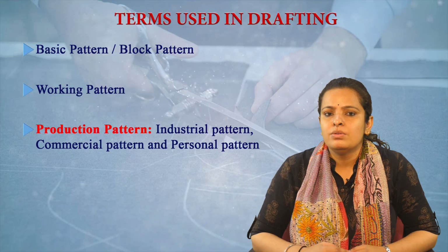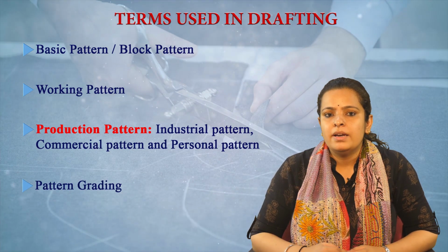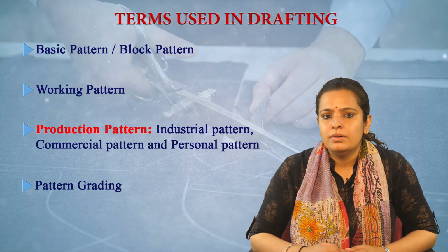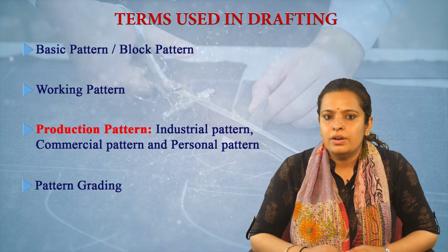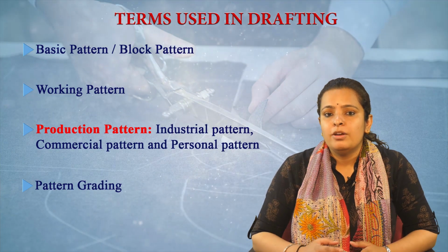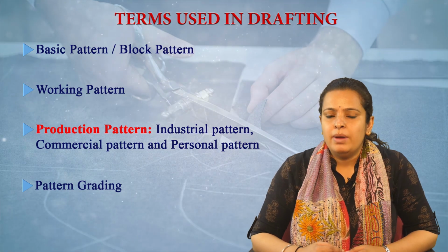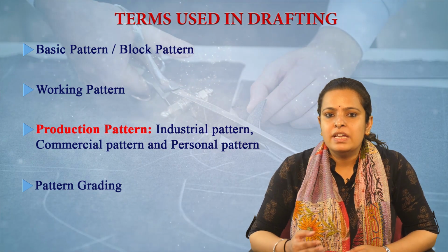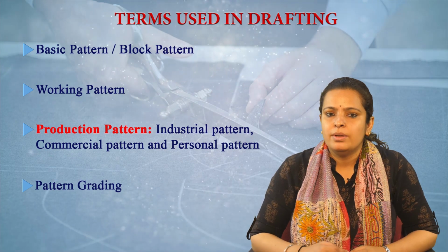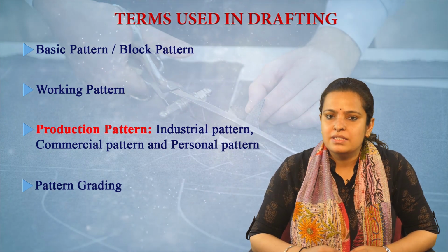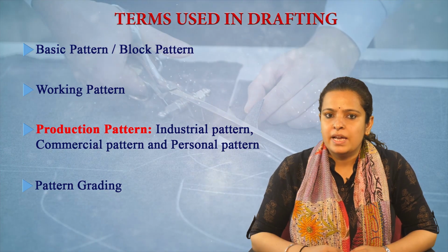Then we use a term called pattern grading. In pattern grading, we create a size range of a particular pattern by manipulating the size of the pattern, in which we increase and decrease the size. So pattern grading is done to create a different range of a particular design.